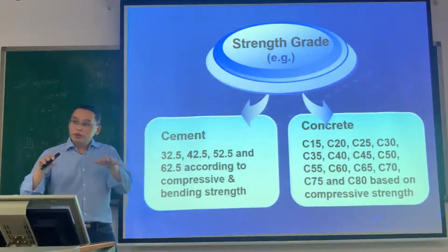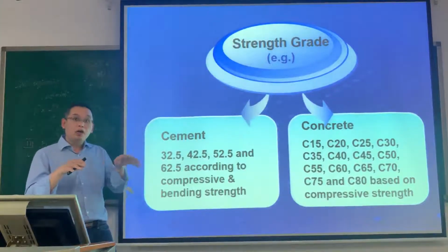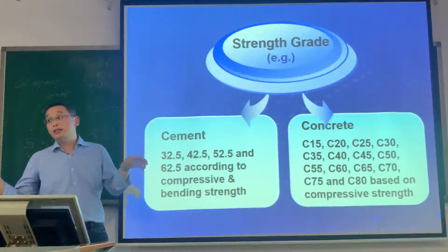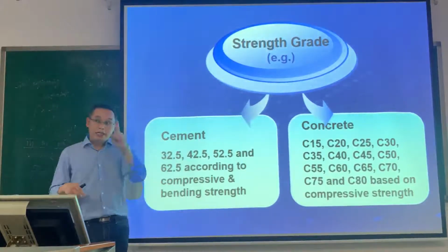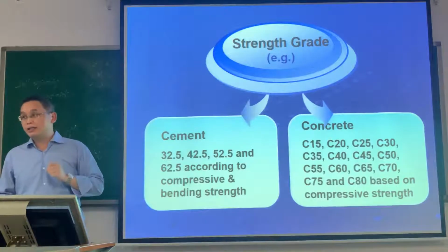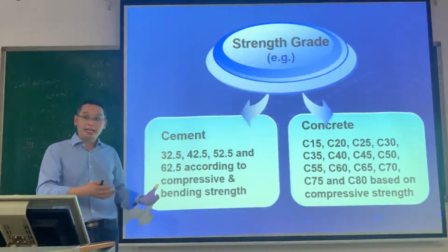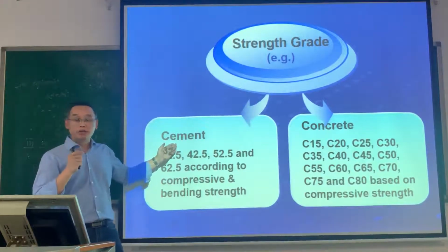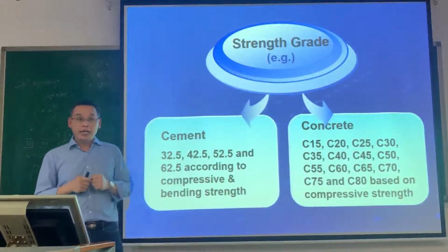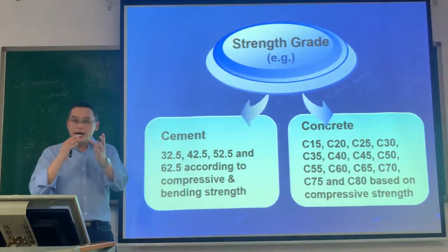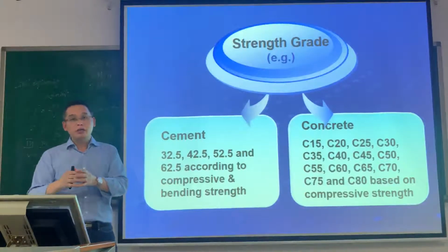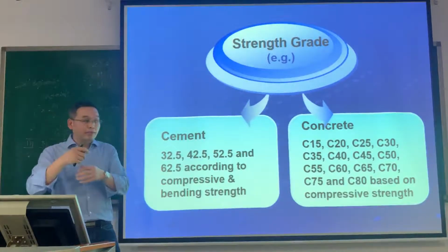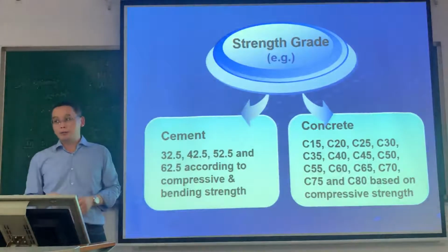Do you get the difference between the cement and concrete? Yeah. The cement is just one kind of product we can get from the plant. And then it is one of the raw materials for the concrete. We need to put the cement, the aggregate, the water, maybe some other admixture together and mix them, and then we can get concrete.